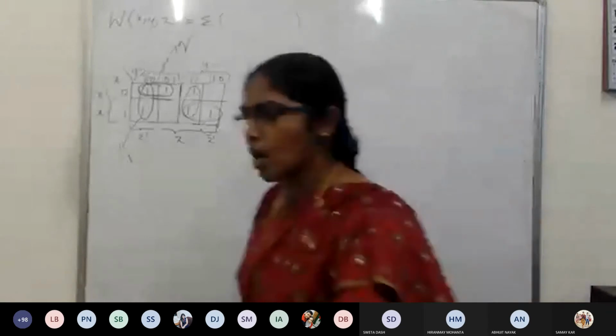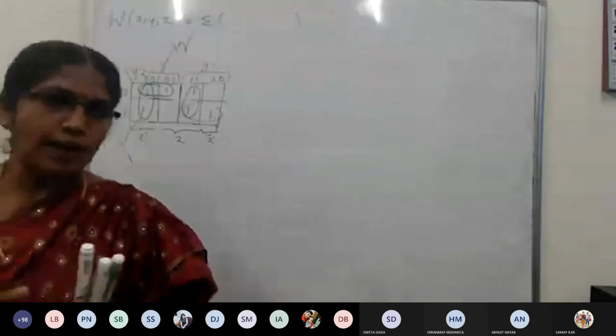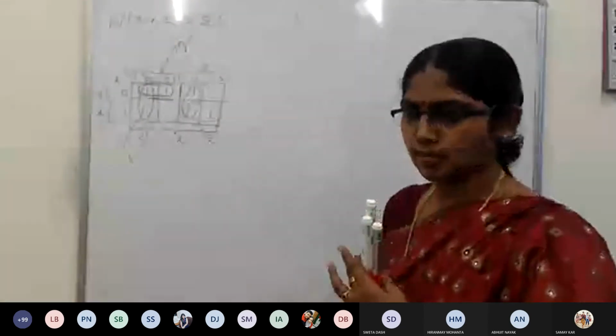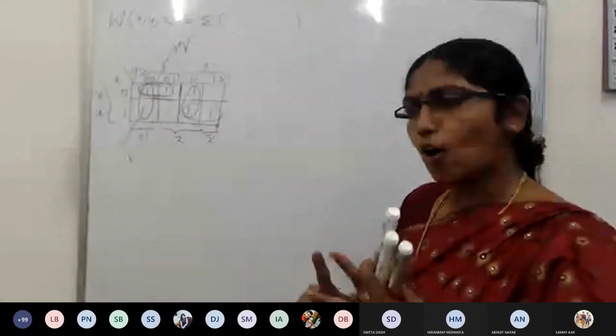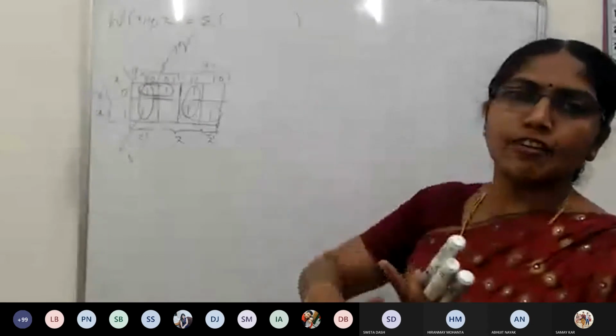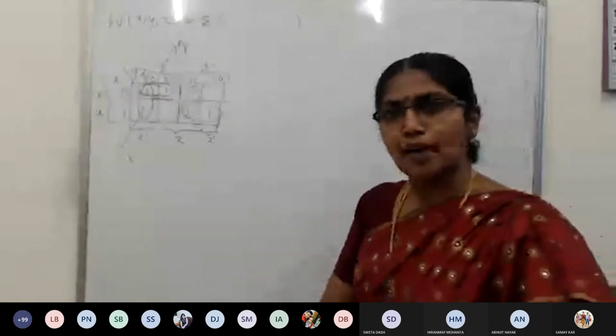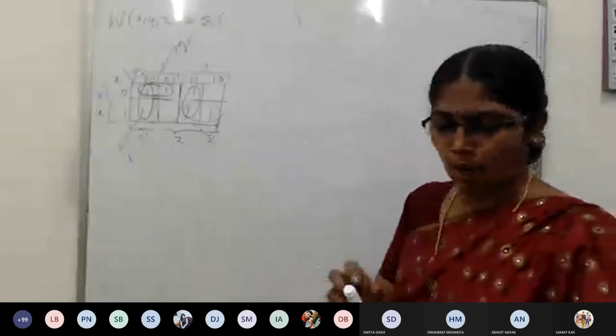So always remember, whenever a problem is provided to you, first aim big: check whether you can make octets or not. Second, if octets are not possible, then think of quadruples, four together. Then go for pairs. So in this problem, this is one option.